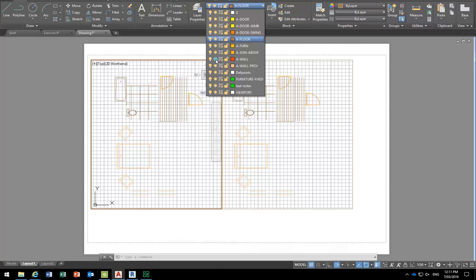And they've got that for reasons, because when you've got big, complex projects, you might have certain things that you want off almost permanently. So that's what you'll use freeze for, the things you want off. You might have all the engineering details in there, but you don't want to work with those. So you freeze them, but then you use the on-off controls for the things you're working with. So that makes it easier. So you've got two different ways of hiding things, really. And it's for management, normally for bigger things.